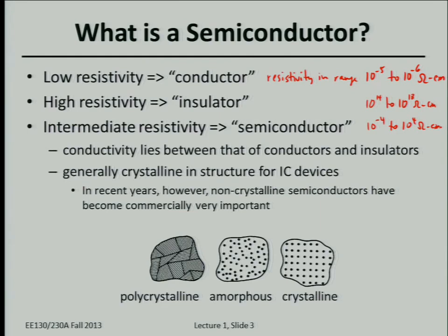On the other end of the spectrum, you have amorphous silicon. And amorphous silicon is actually what's used in flat panel displays. When I said that there was 1 transistor per picture element in a flat panel display controlling the brightness, those transistors are made with thin films of silicon coated onto the surface of a piece of glass. And because of the way you deposit the silicon on the surface, the atoms are not really well lined up with each other.